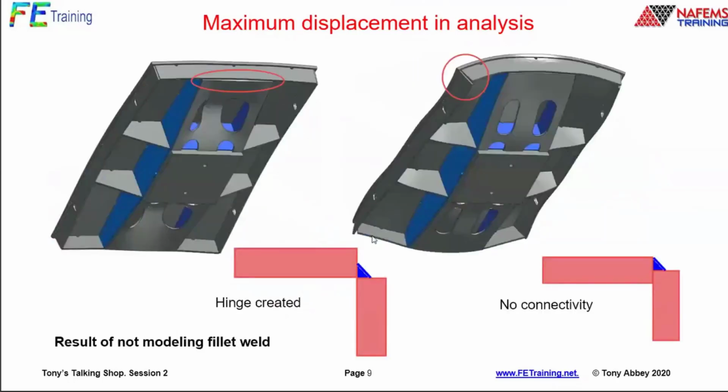This again is a normal modes analysis. This was interesting. This was a combination of training and also mentoring at a particular client site. So this was a bunch of designers, and they were producing this platen here, for example. It's all solid steel sheets, and it's fillet welded together. For the design, there's no reason to actually model the fillet welds. They're just called out, and they're not necessary to put in.